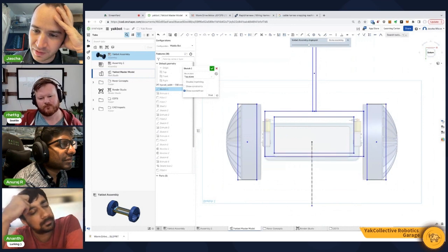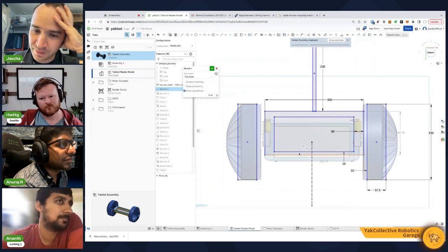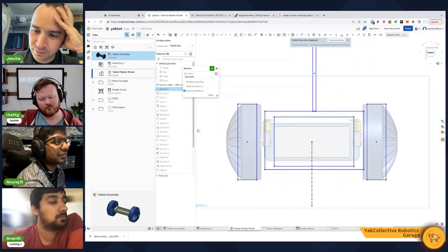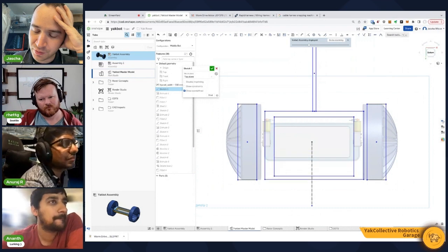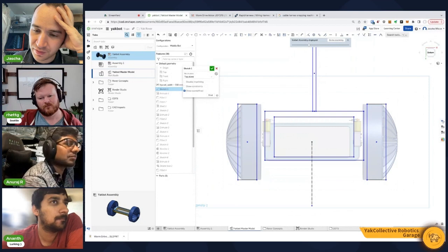I think the biggest thing I would question is that if we have a camera with a wide FOV mounted on the front, we're going to have occlusion from the wheels. So this gives us no occlusion for a wide FOV camera. This occludes us by some amount, given a center-mounted camera.